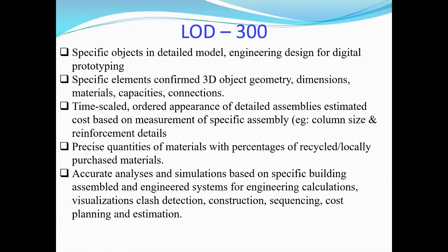Okay, the LOD 300. So this is the maximum level Singapore consultants are doing so far, right? So in this level, we are putting all rebar details. So 100 series is a concept, 200 series we further develop, so you can see the geometry. 300 series is equivalent to our tender documentation modeling, equivalent to documentation, 300 series in Singapore terms.